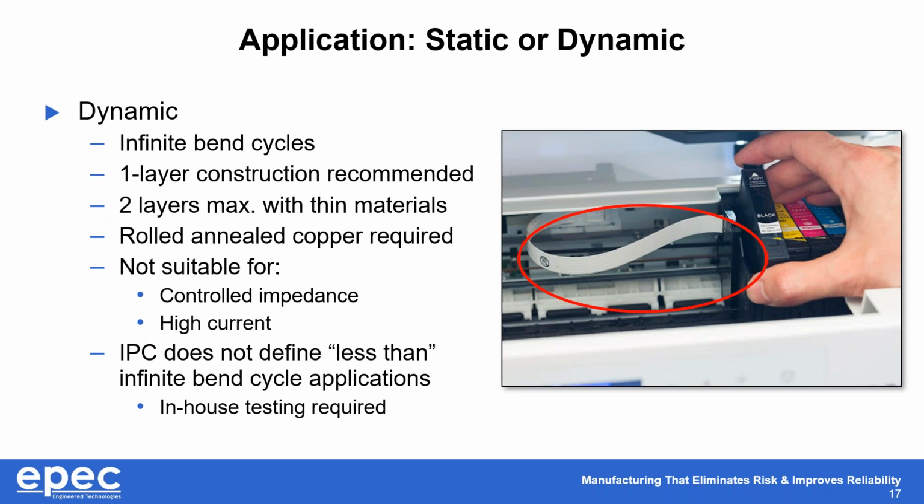Dynamic applications are not suitable for controlled impedance or high current. The impact that controlled impedance and high current have on the thickness of the design, in the vast majority of cases, will not meet the bend requirements.